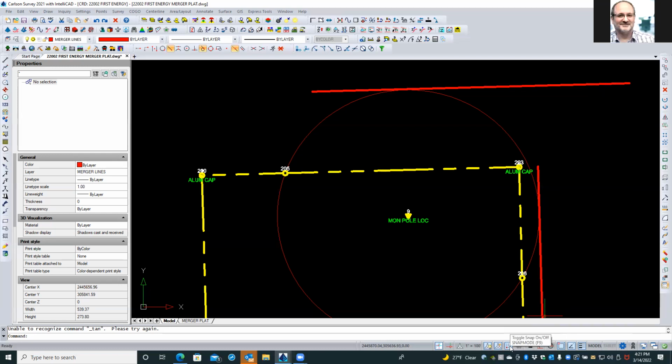Right there, yes. Because that'll lock you into those grid settings, like every 5 feet or whatever the settings are set to. So if you were an architect drawing buildings on a 30-foot grid, you could set up a 30-foot grid spacing and everything locks to the nearest grid spot.